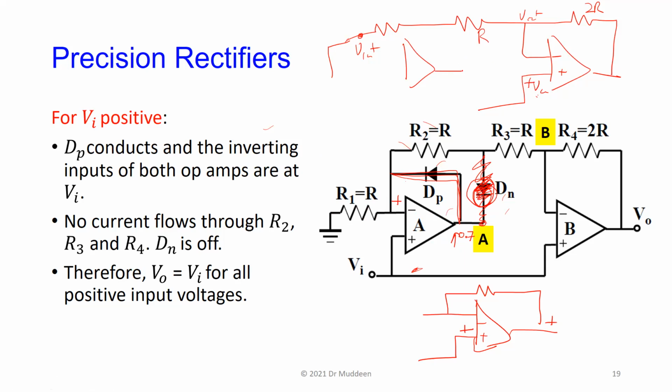So in other words, this is what you have. The op amp has this kind of arrangement here. You have a short circuit between the non-inverting input and the output, more or less. The output is holding itself at 0.7 volts, but nothing connects this op amp to anybody else. It's just floating, so it has no part to play in the circuit. So the resistances associated with that op amp are out of the circuit.